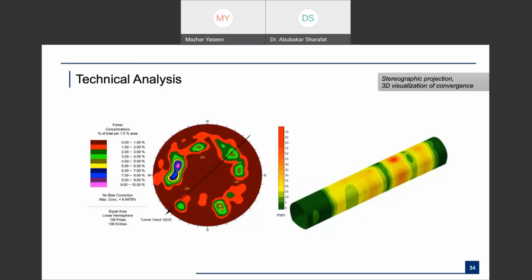But in case we have a running tunnel, or it is post construction, let's take the example of the Swat motorway tunnel, then of course the problem is that running LiDAR scanning every day can disrupt traffic. Or if it's a hydropower tunnel, it's almost impossible; you cannot go inside the hydropower tunnel. It's different in a hydropower tunnel. Normally we don't have convergence once we fill the tunnels, but in the case of a road tunnel, we can use the convergence stations, and we try to disrupt as little as possible.